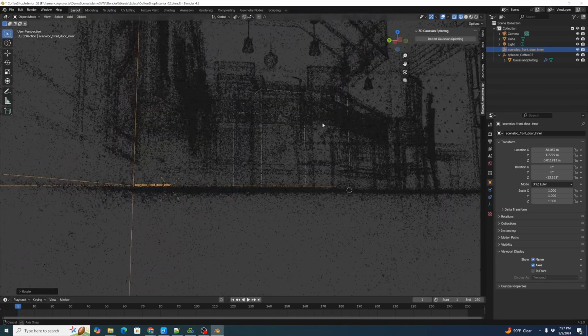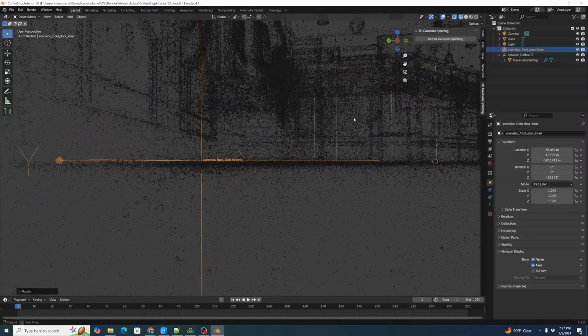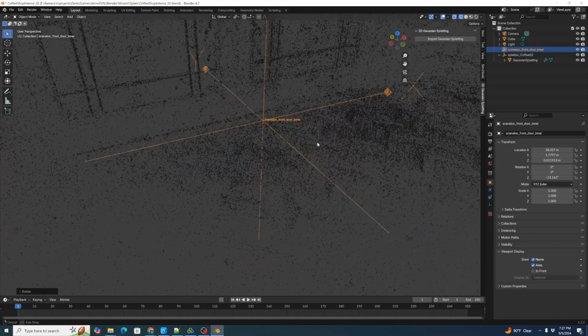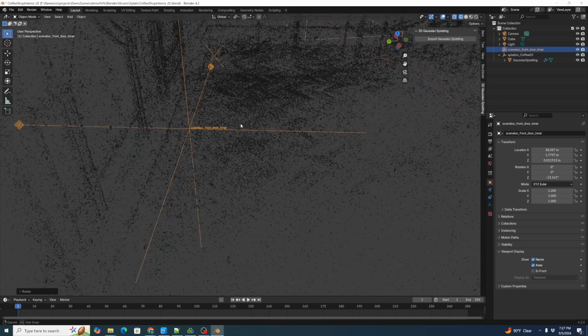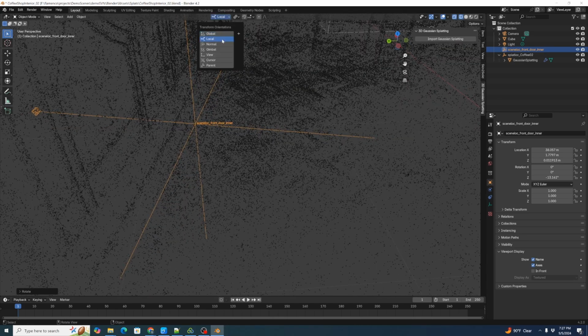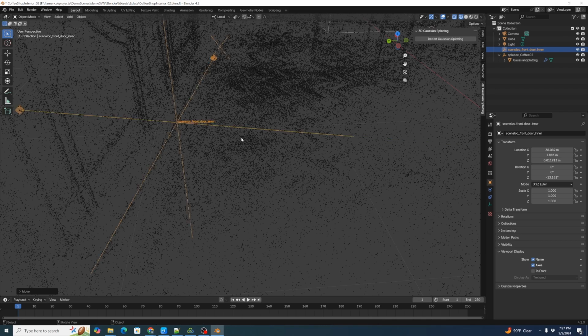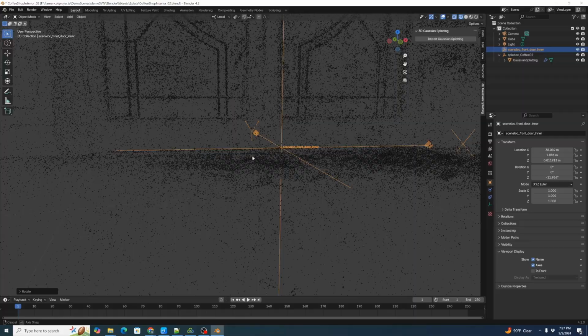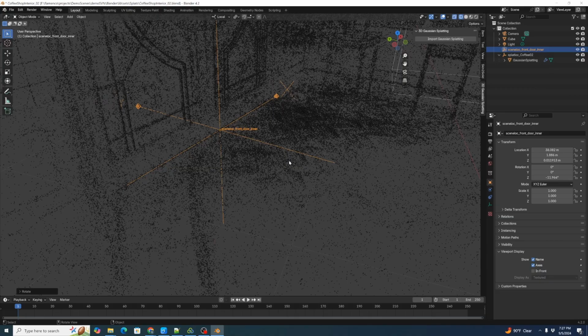Now we can align our scene locator closely to the floor. Again, this is a little bit of approximation because the Gaussian splats are a bit more statistical. And while we're looking at this, we can get it to line up closer. Let's go ahead and adjust along the local transform. That way, when I hit G and can move along these axes, I can come up to here, hit RZ, and align this with the edges of the door precisely. And then we can see that we are pretty well aligned in 3D space. There we go. And it is the scene loc front door inner.